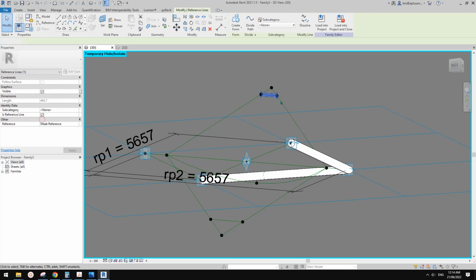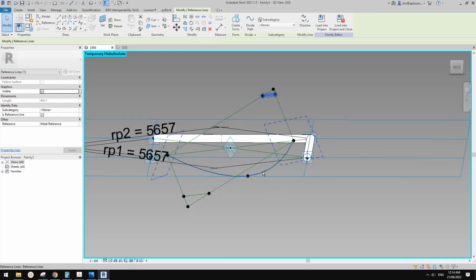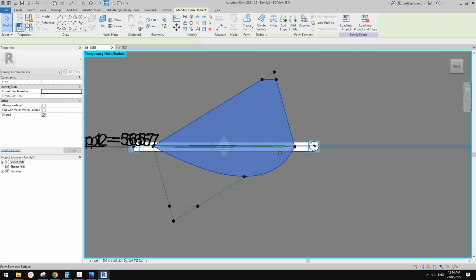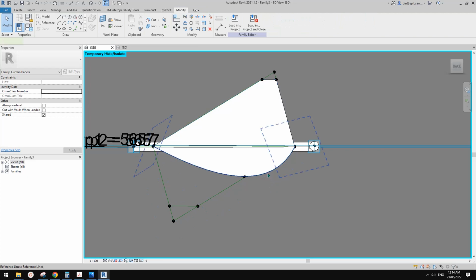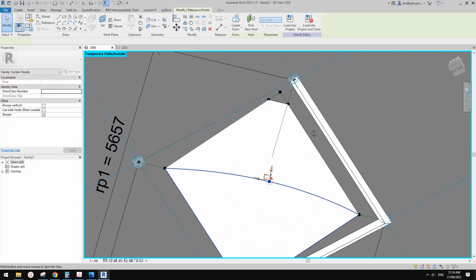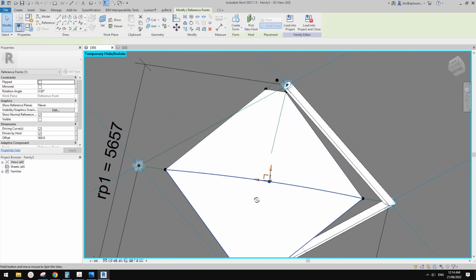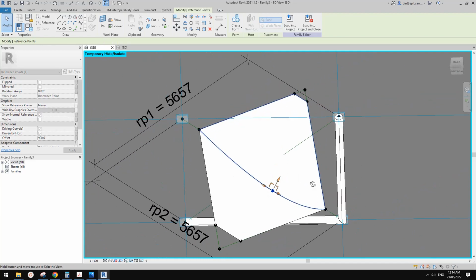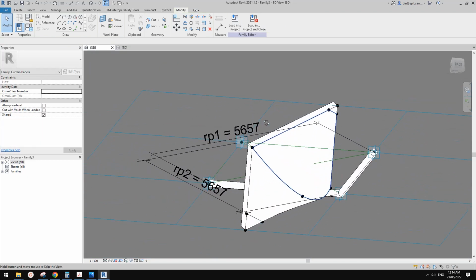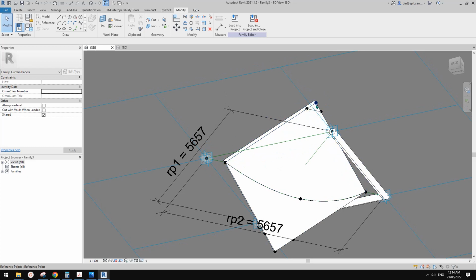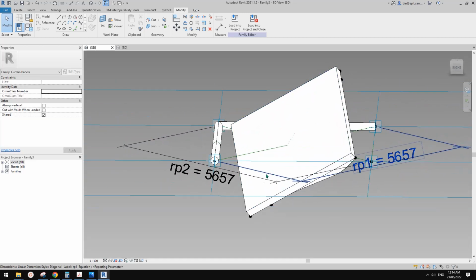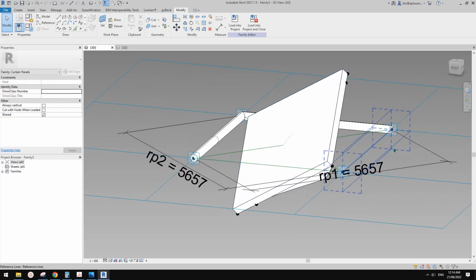And then we can use a reference line together with this arc to create a form. Try to select the arc, yeah, oops, wrong one, this one, yeah, and this, create a form. And if you want to, you can also offset this arc. Currently it's sitting in the middle, so you can offset it, something like this. And hide, so we still have the solid part. Oh, hang on, so we have that, yeah, we need to cut these two triangles. So that's fine, we can do this.